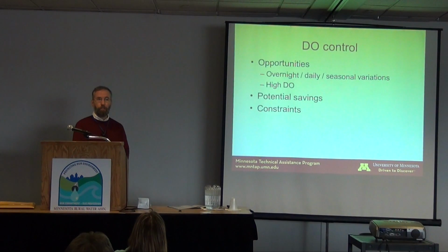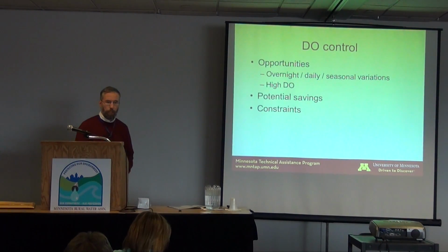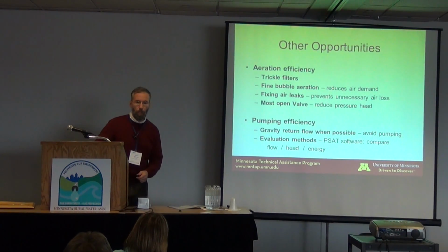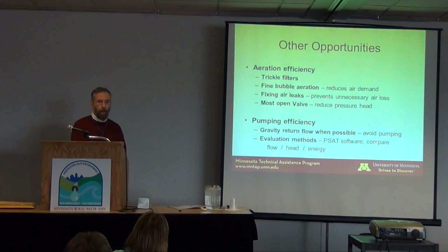There are a number of factors that have to be accounted for. The blowers have to be the right size. If the blowers or your aeration equipment is already operating at its minimum, it's hard to get any lower with DO. And you do need the controls and reliable sensors. The next. Other kinds of opportunities.